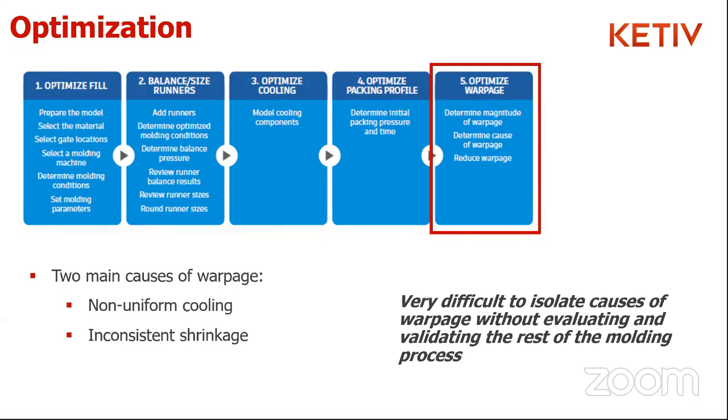That's a good point. In regards to adding detail, that avalanche of detail I mentioned earlier, upfront, you certainly can make some assumptions and see geometry effects with, say, ideal cooling, uniform mold temperature, but you might miss something. Shrinkage is quite complex through thickness, region to region, and even orientation effects can sometimes be identified early on.